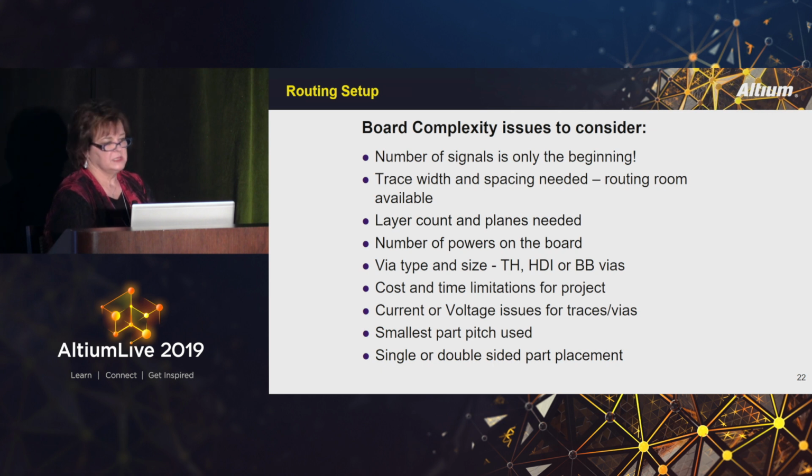And you might have cost and time limitations for your project. Is that more important than doing the board in the most signal integrity qualified manner? What about current and voltage issues, and trace sizes and via sizes because of that? What is your smallest pitch part on the board?